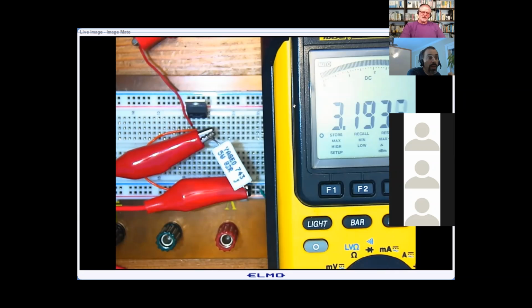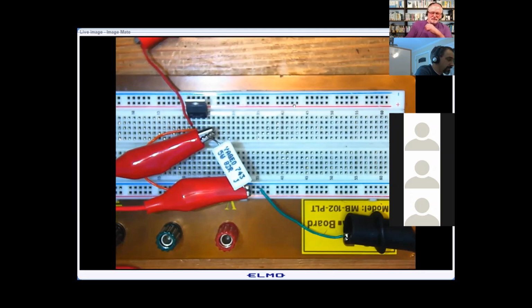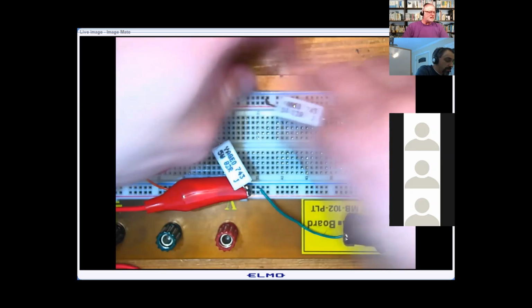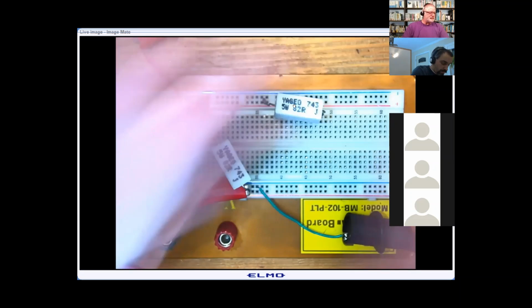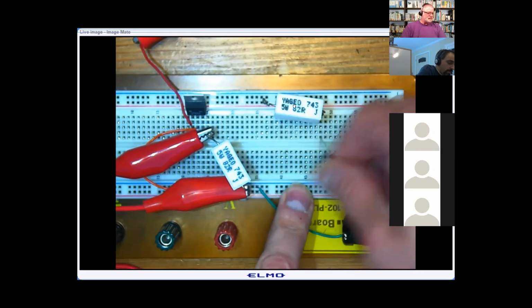thing. So does the Zener have a voltage penalty like the other diodes do? Let's investigate that real quick too. It's not a bad idea to investigate that. I'm going to use the 6.3 volt regulator Zener with my 82 ohms. So what I'm going to do is just change out the leads on this. Similar setup.